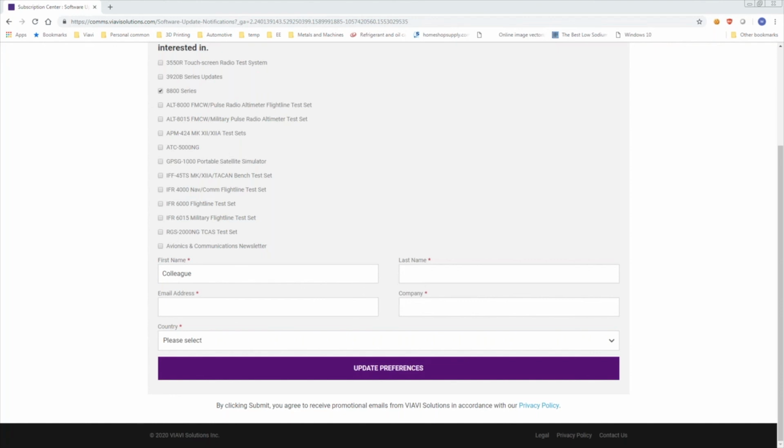Well, any loss for the RF adapters, if you don't know what it is, when we use those calculators, we usually just say 0.025 for however many adapters you've got in. If you've got 4 in there, 0.025 times 4, that'll probably get you close to what you're seeing. Yeah.